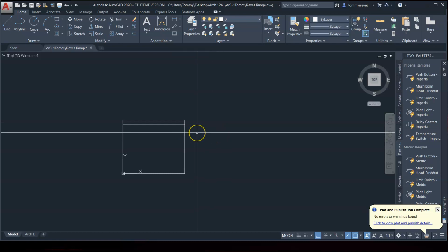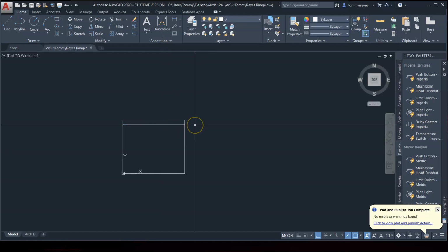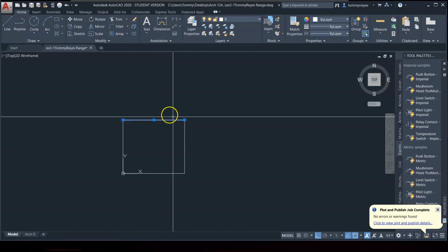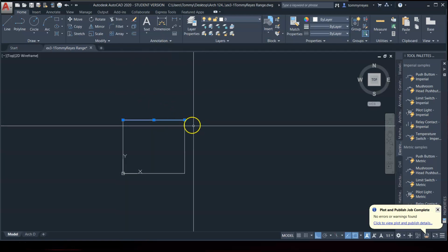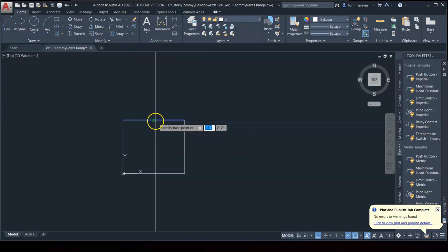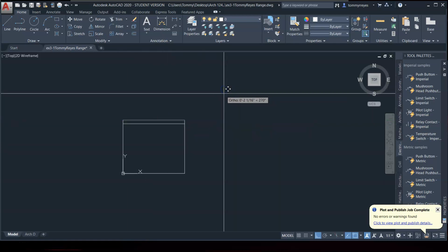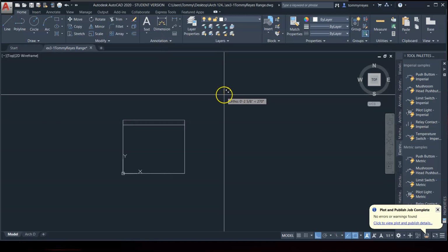And that was the letter M for move. You see that again. It's Control Z. So L for line, create a line from here to here. I use the endpoints. Letter M, spacebar, and I just random displacement. I'm just going to left click over here and down 2 inches. There you go. All right, now it's saying to make 2 circles. And it looks like these circles are going to be 9.5 inch diameter and 7.5 inch diameter.